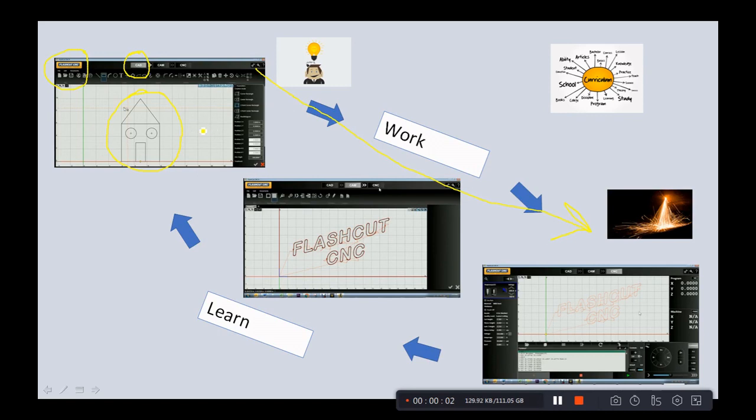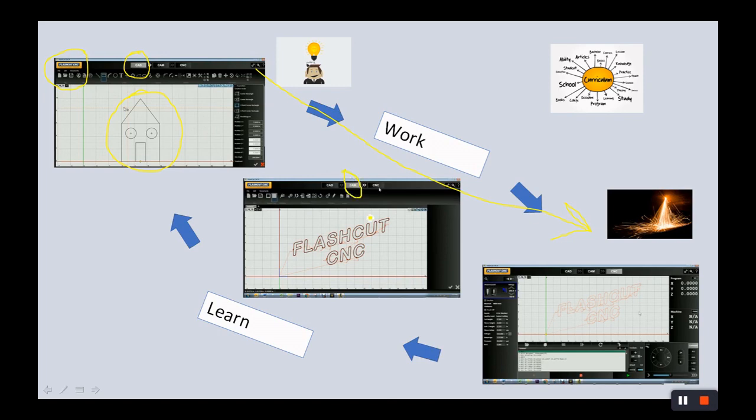After you have your drawing, the next step is the CAM, which it might be hard to see here, but all these little dashed lines, that's the tool path that the torch takes. Is it going to cut on the outside of the F or on the inside of the F? And what is the path that it takes to get all these done?